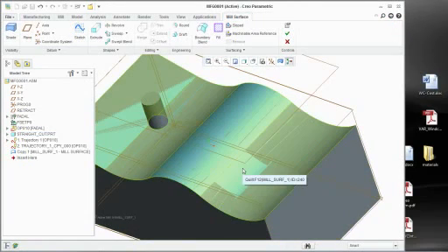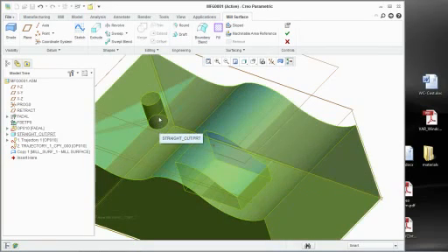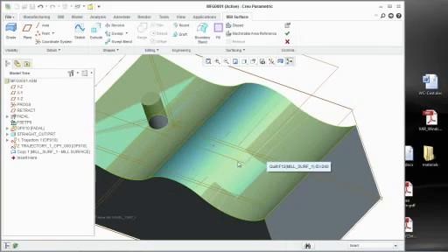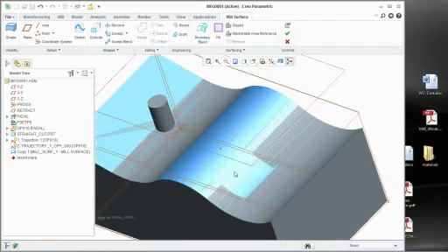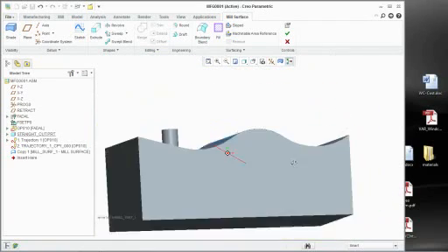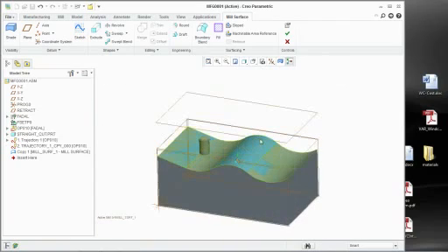Now, I actually think that's something that was in previous versions of the software, but it's just a way to, when you do copy and paste for mill geometry for a number of different reasons, you have those gaps, and it easily fills in gaps, whether it's a hole gap that we want to do right here, or a gap that you see right here. It fills that up, and essentially what you keep is the same geometry, the same contours that you would have before, and now it just machines over the correct way. Okay? So, quick little help and tidbit about that.